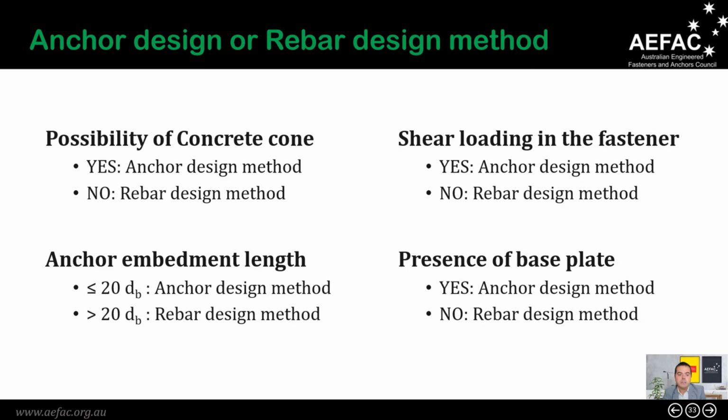And another one is in terms of embedment depth. If the embedment depth is less than or equal to 20 times the diameter of the bar, we can use the anchor design model. And if it's more than 20 d, we cannot use the anchor design model. We have to use a rebar design method.